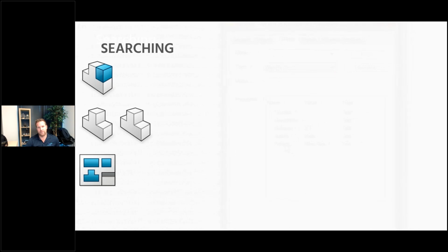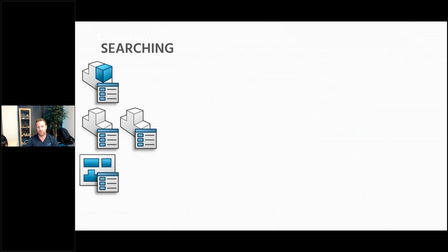Working inside of PDM, as I mentioned before, it has SQL on the back end, so there is information, metadata or properties stored with all of those files, and we can search on all of that in the vault at any point in time. Because it is using SQL, it's almost instantaneous, and it's an iterative search. That means I can search for, say, bracket in my entire vault, and yes, in my vault you get a very long return, a big list.